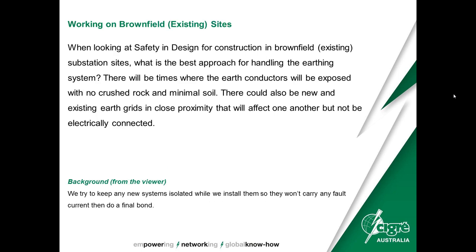Okay, great. Thanks, Stephen. Next question is about brownfield or existing sites. When looking at safety and design for construction in a brownfield substation site, what is the best approach for handling the earthing system? There will be times when the earth conductors will be exposed with no crushed rock and minimal soil. There could also be new and existing earth grids in close proximity that will affect one another but may not be electrically connected.